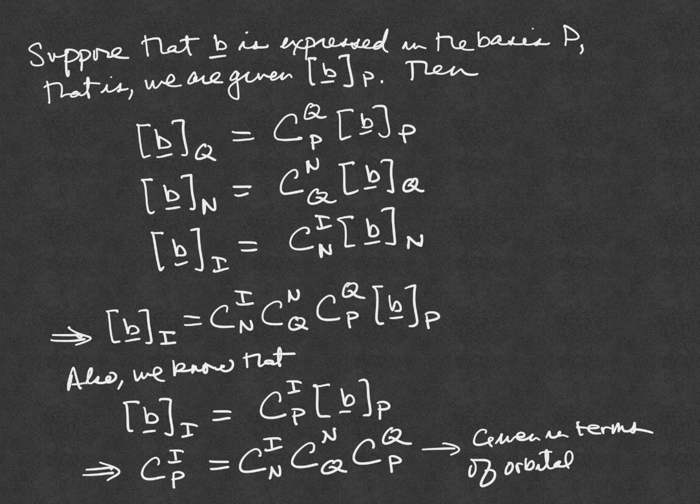And in fact, it's only given in terms of 3 of the orbital elements because we don't need any of the other 3. We only need those 3 Euler angles to be able to do it. So this is purely a function of the angle big omega, little i, and little omega. And that gives us that transformation. So now the next part is we need to figure out how to express the position and the velocity in terms of the perifocal basis. Because once we have that, we're done with this entire process.